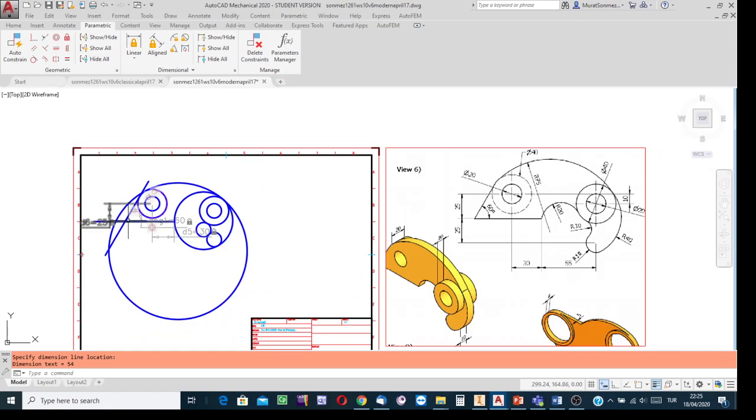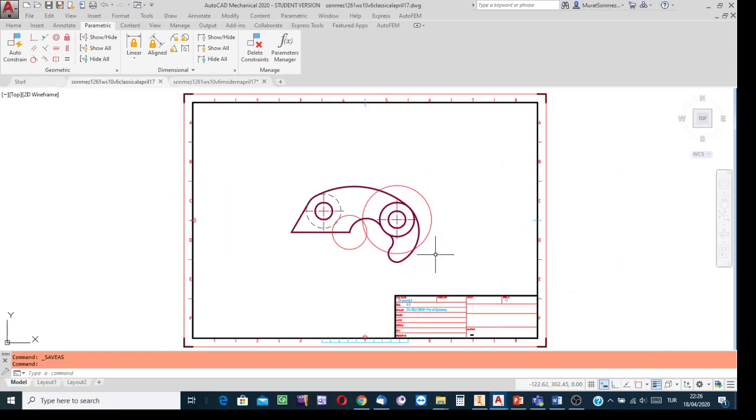After trimming, of course, it will find its other terminal point and also the tangent point at the correct place. But here, trimming is not allowed. To be able to create this boundary in the classical method, what we have are construction lines. About this point, create a circle. About the center of the available one, create that circle.